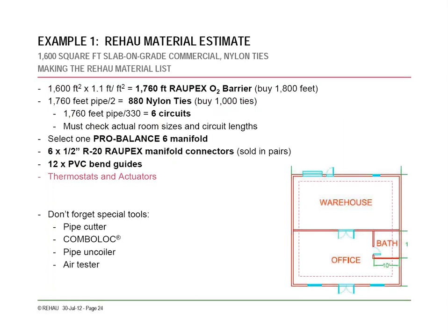All right, so we're back in our material estimate example. We've calculated that we have 1,760 feet of pipe. They show 1,800 feet here. This is really going to depend on your circuit length and the tubing sizes available from the manufacturer. I mentioned 300 feet before. Half-inch pipe is sold in 300-foot lengths. You can just buy the number of circuits you need. Makes it nice and easy. The ties, in our Uponor case, come in packages of 2,000, so that makes it nice and simple.